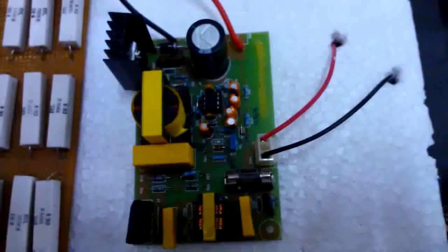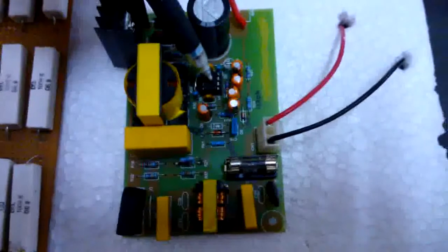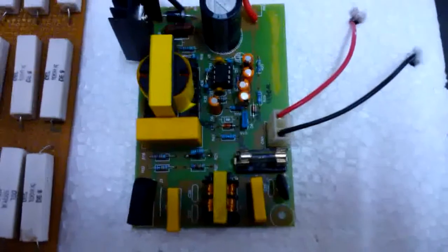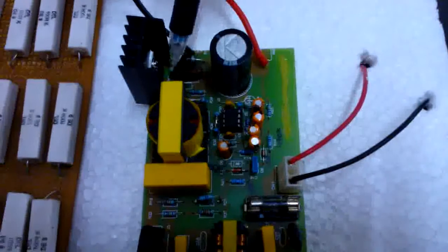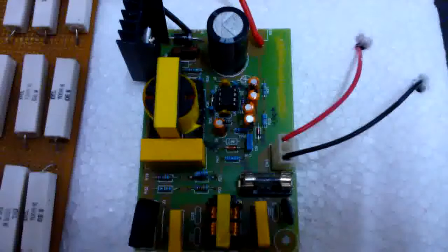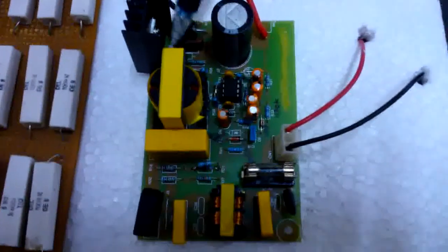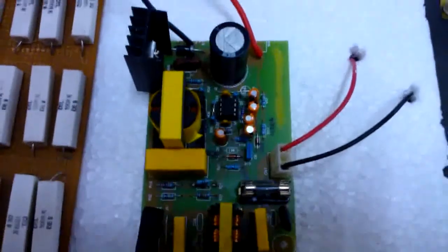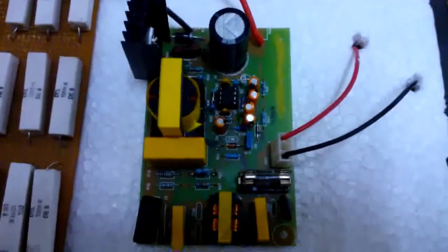And this is the boost capacitance. Coming to the IC, pin 1 is the output voltage as feedback via a potential divider, and pin 3 is a measurement of the pulsating DC via a potential divider. Pin 4 is the current sense through the MOSFET, pin 5 is the current sense through the inductor, the 6th pin is the ground terminal, and the 7th pin is the pulse which is given to the gate of the MOSFET. The 8th pin is given an 18 volt input through the Zener diode.